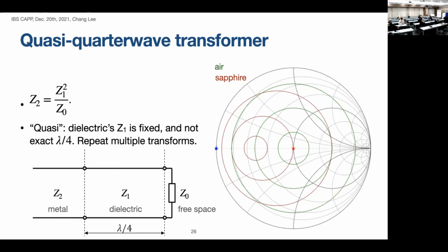So in this process, what actually changed in the physical system? The dielectric constant doesn't change. Dielectric constant is already fixed, and you have to live with a fixed thickness. So the electrical length of your dielectric is not exactly quarter wavelength. But it's something. If it were exactly quarter wavelength, then you would end up here. But you are not quite there, and then you have to compensate. So you have to compensate the rest with the air. So first you need a quarter wavelength of air, but there's a slight offset between this and where your dielectrics end. So you add the addition to the distance.